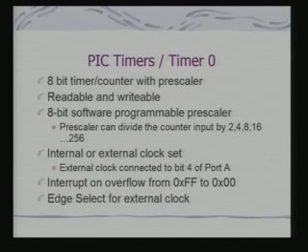So, effectively what I am doing is increasing the range and the time period over which the timer can really count. These timers are readable and writable. So, I can read the current count as well as write to modify it.